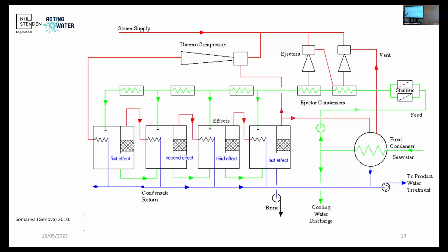So the showers will be showering on top of the tube bundle. In this tube bundle, you have your evaporated phase. This evaporated part of your feed will be collected to pass to the next tube bundle. I think you can see here. A fraction of this showered water which evaporates passes through a demister, and it will be injected in the second condenser, which will then be showered by the second shower.